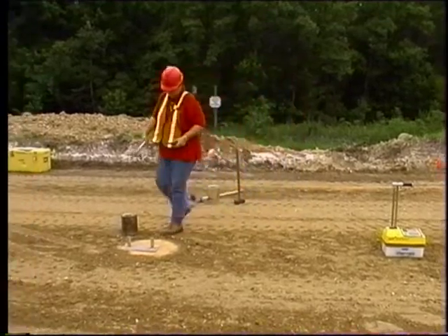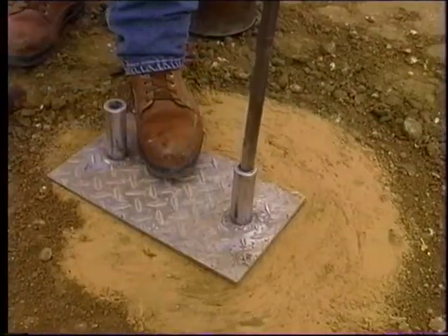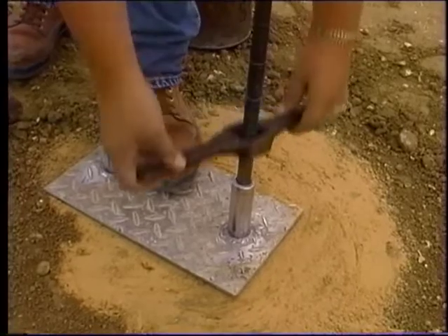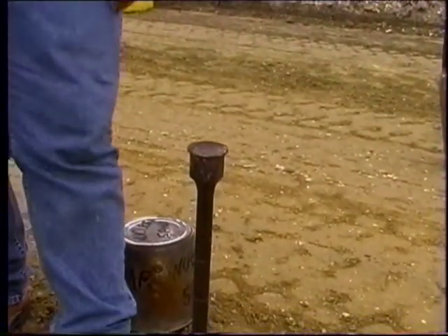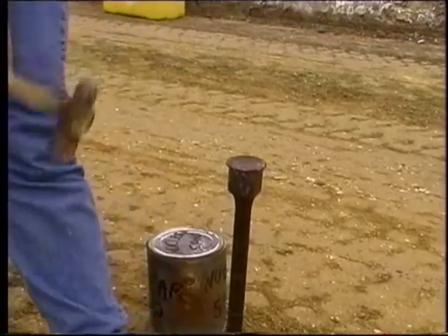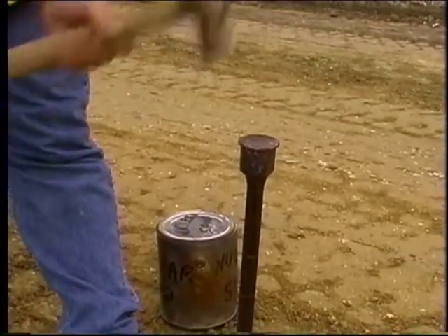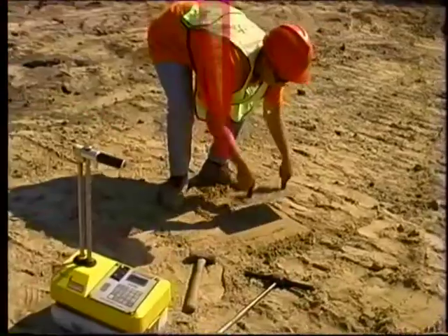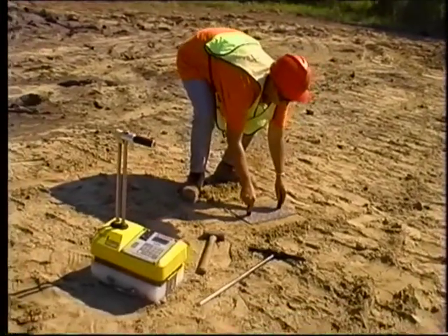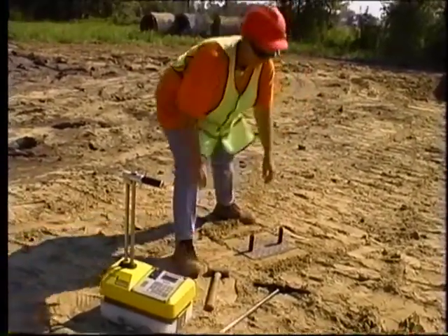Identify and set the test depth to be used. The test depth must be the deepest setting possible that will not penetrate beneath the lift of the material being tested. For example, the source rod can be set in 1-inch settings. If you have an 8.5-inch base course, you would set the rod at 8 inches.